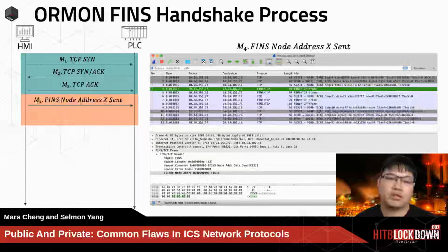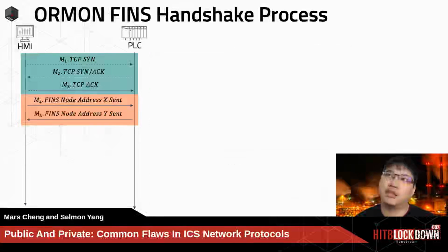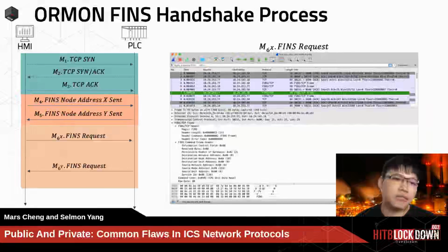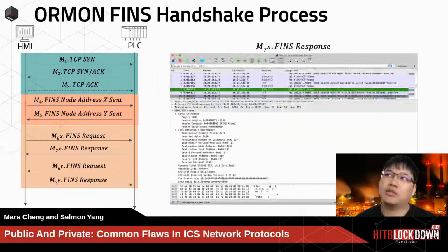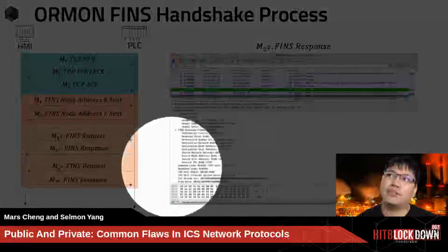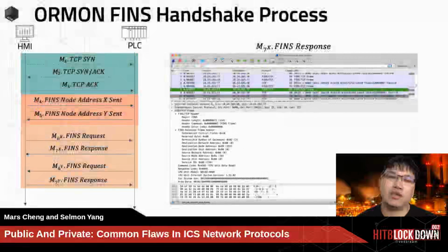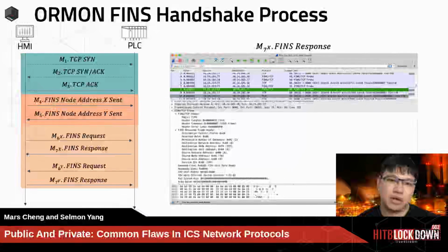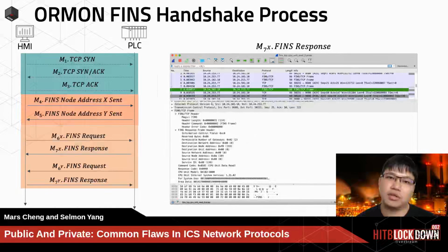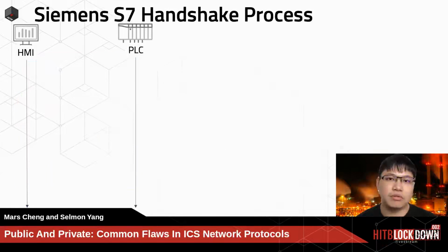So in each traffic, each communication, you will see address sent or feedback, request, response. You will see all of them are plain text passwords for system use, or every piece of information is plain text. So no encryption and also no authentication and authorization. So it's a very weak protocol, even though it is a private protocol.